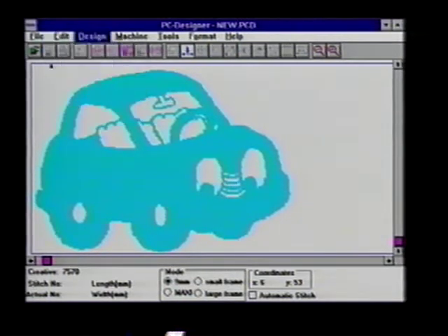Design is really exciting. Click on Design. It is here that you can load, fade in or fade out, and delete BMP template files. A BMP is a bitmapped graphic file format. It is used in PC Designer as a template or guide in setting stitches. You can scan or draw your own template in any graphic software application that allows you to save your work as a black and white, uncompressed BMP file. We will be using your Windows Paintbrush program to create your own BMP file.